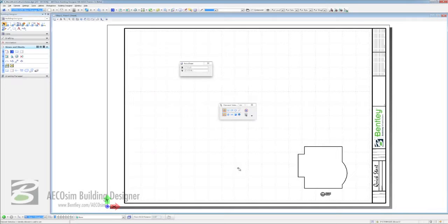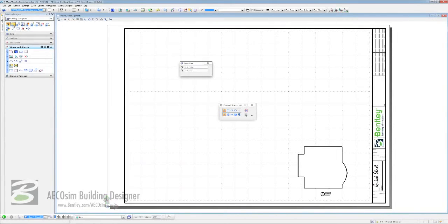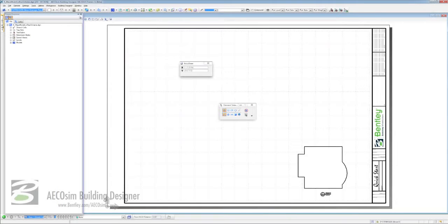We're going to place our 2nd and 4th floors alongside of this, and the most efficient way of doing this is to use something called Project Explorer. To do this, you go up to your primary taskbar and you'll see there's an icon called Project Explorer. If you click on that, you'll see it appears to the left-hand side of your task-based interface. Pass your cursor over it and click on the Links tab, and below that on the jump box select the Building Arch Local, and then twirl down Drawings and All Drawings. And you'll see that we have floor 1, 2 and 4.